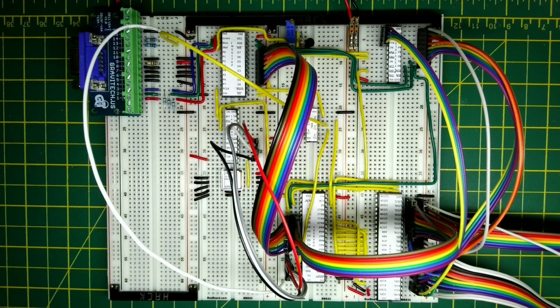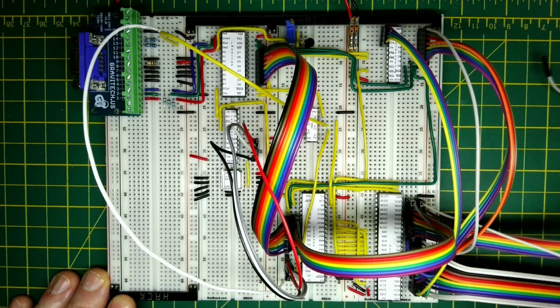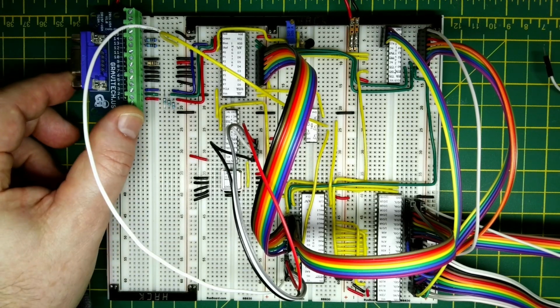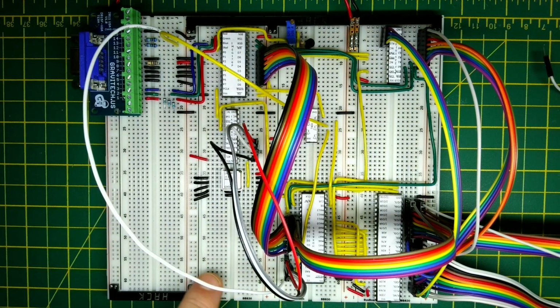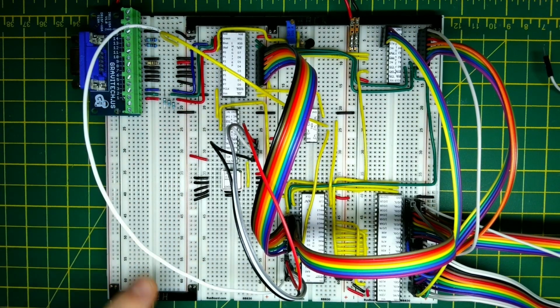Okay, so that's the board pretty much wired up. All we're going to need to do is to wire these various fly leads into the main computer board onto the bus rails and things, but we should have enough now that we can plug in a VGA monitor here and get some sort of signals coming out. We're going to need to feed into the video DAC some signals which I'll probably derive from some of the memory address lines down here, and it just means that every couple of characters the colours will change. So I'm going to break the video now.